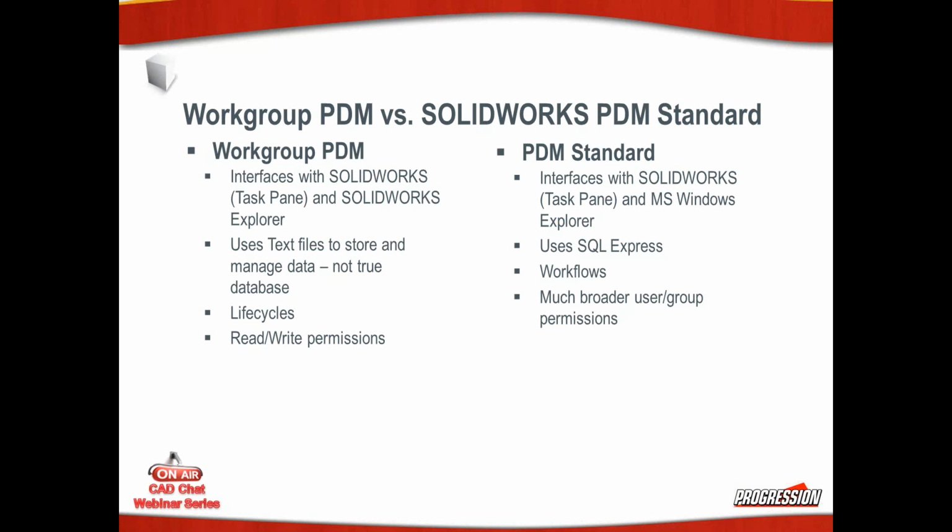What we find in Workgroup PDM as well is, I don't want to say a limitation, but somewhat limited read-write permissions. You can have read permissions or read-write permissions to a given project and folders and files. Within PDM Standard, you'll see that there's a much broader user and group permissions capability, covering everything from the ability to read the files in a given state to checking them out, deleting them, and so on. So it's a very robust product given the permissions that might be required for your local work group. That's just a few of the differences.